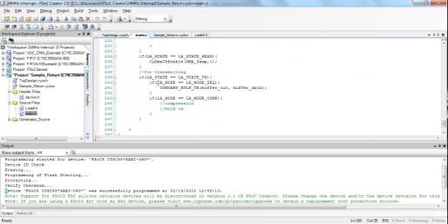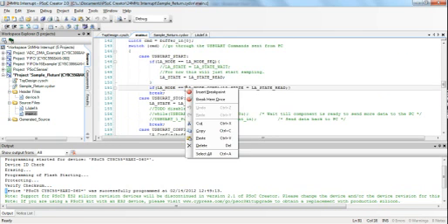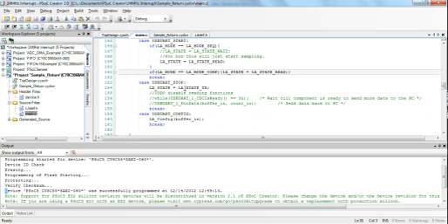Once it's in transmit, it goes to USB bulk transfer and tells it to send all the data it needs to. It sends 64 bytes every time this is sent, and it just continues to repeat as this flag continues to be hit up here until the process is done. Like I said, the second video will show this actually working with me sending to the terminal, and this is just an explanation of the code and how it works.